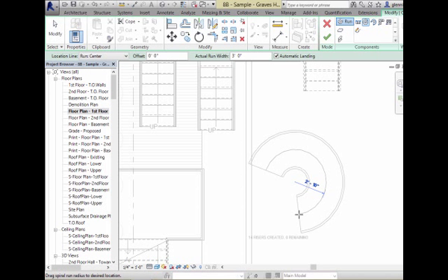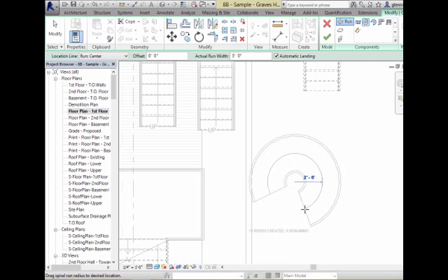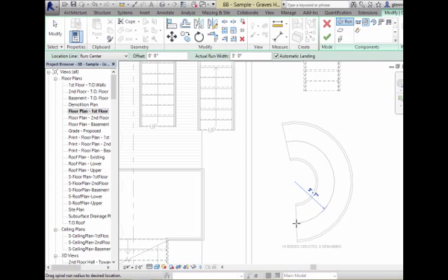Because stairs actually have their own rhythm to them. They don't really want to be much more than 10 inches deep at the center point, because then it'll be too long a stride to get up there. So as I pull this out and give it a bigger radius, each individual stair is tracking in here. It's really 14 steps along the run. So what happens is if the stair gets very broad, it takes less and less of the full corkscrew to get up. If the stair gets very small and teeny tiny, it'll actually even double back on itself. So what's happening here is just based on the width of the stair, or I guess the radius of the turn.